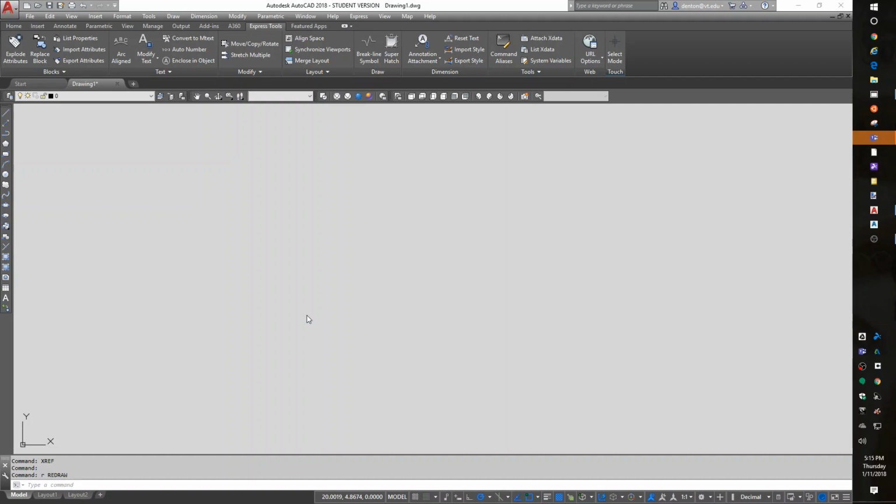But to begin the discussion, I need something to use in Paperspace, so I'm going to xref attach in the baseball field, make a drawing, and then go into Paperspace, put in a border, zoom it to scale, put in a north arrow, graphic scale, all that type of thing. I'm actually even going to rotate a view, try to do a little bit of everything with Paperspace.